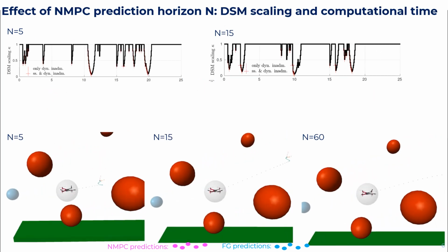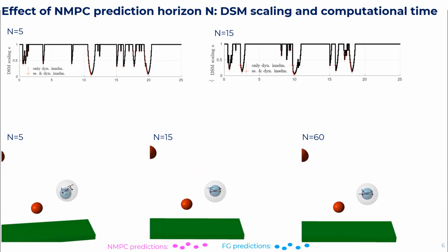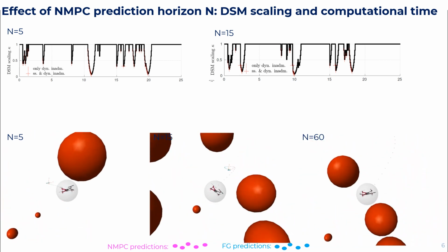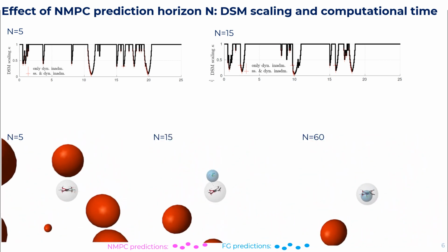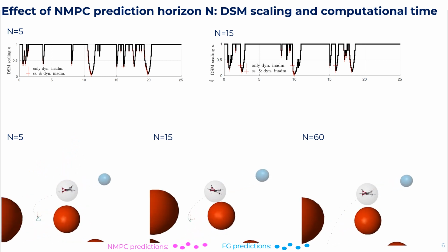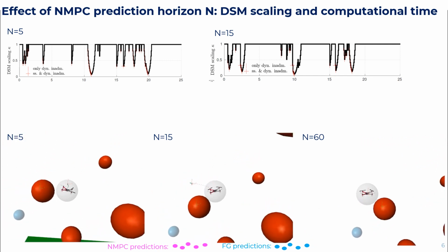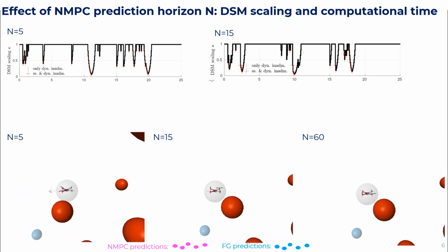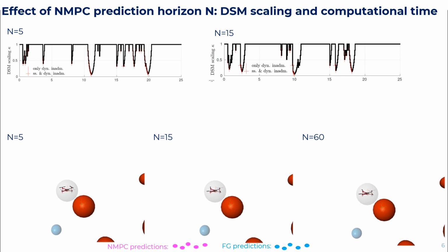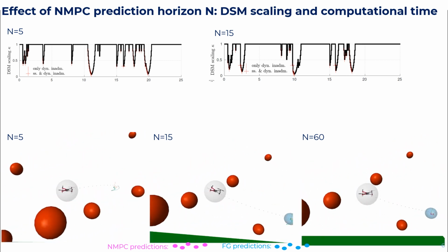This FG method relies on a discrete-time implementation of a continuous-time ERG law and is based on integrating the auxiliary reference velocity with a time-varying step length, which is reduced with a fixed reduction rate whenever the auxiliary reference guess results in a trajectory that is steady-state or dynamically inadmissible. If it is admissible, the scaling factor can be increased again to possibly speed up convergence at the next sampling instant.